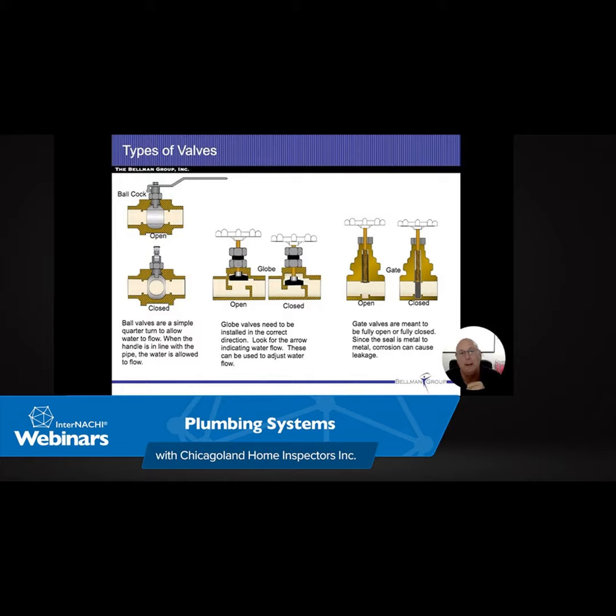All right, this one was just kind of a no-brainer. We got a gas water heater up on there, and there's no vent connector on the top. We also have a pressure relief valve on there that doesn't have a discharge tube as well.